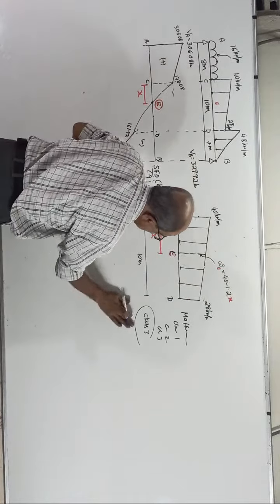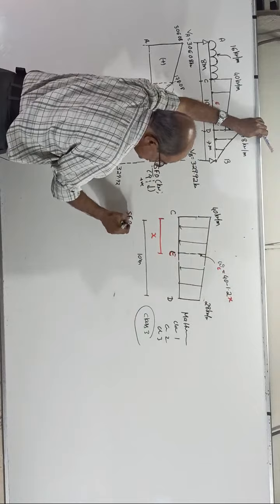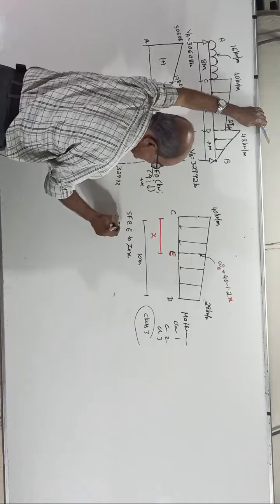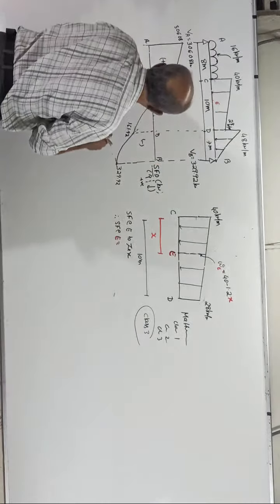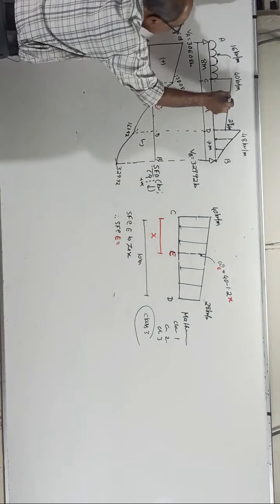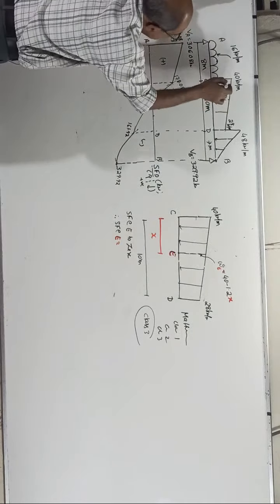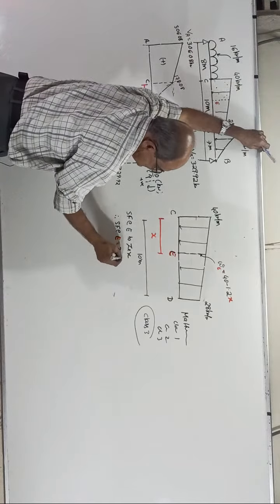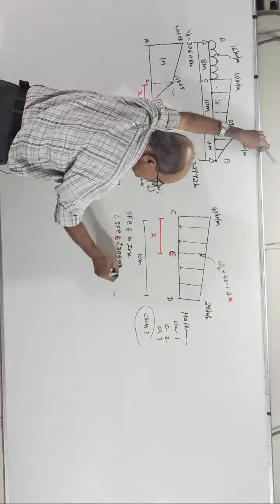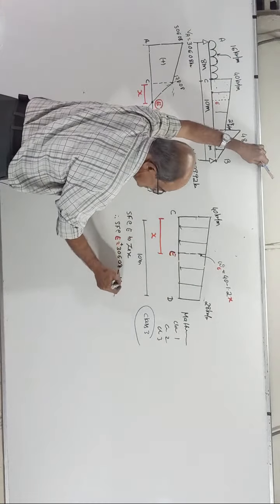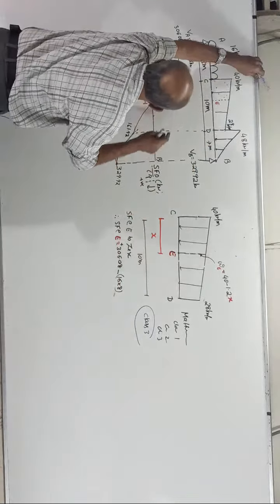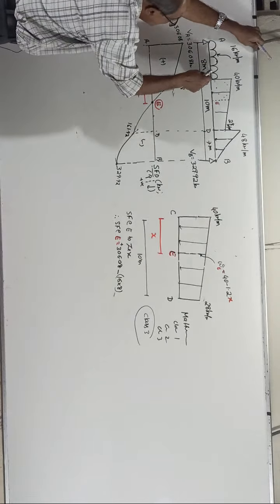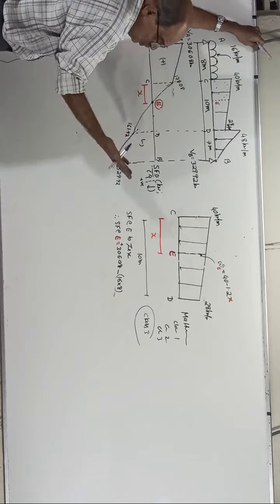Now start. I told you to equate the shear force at E to 0. Therefore, shear force at E equals, start here. Somewhere here is the ordinate. Look this side, start: plus 306.08, minus 16 into 8, actually not required because that is equal to 178.08. You can start from here only, at the left hand, 178.08. Continue. Okay, do it.